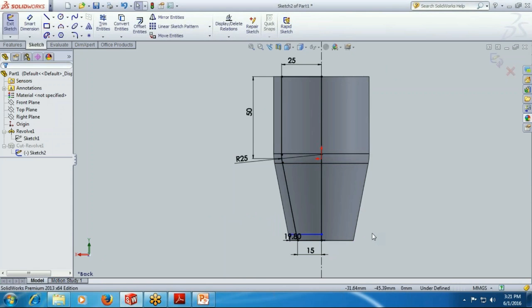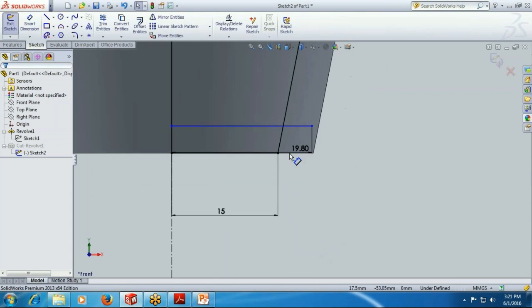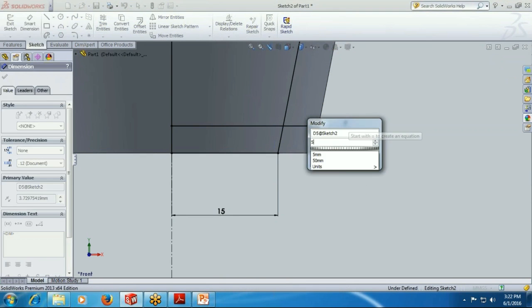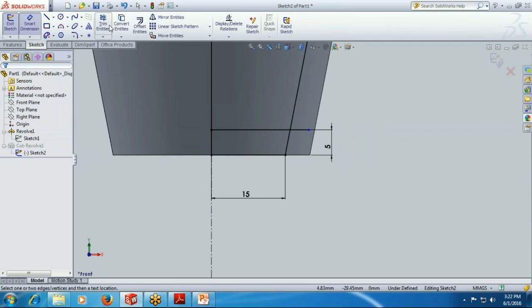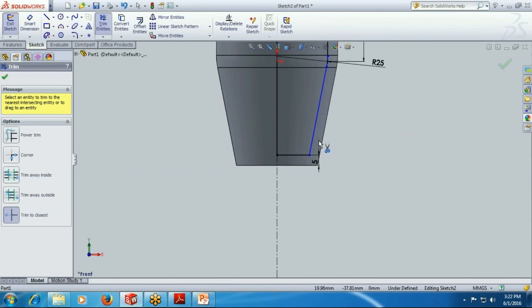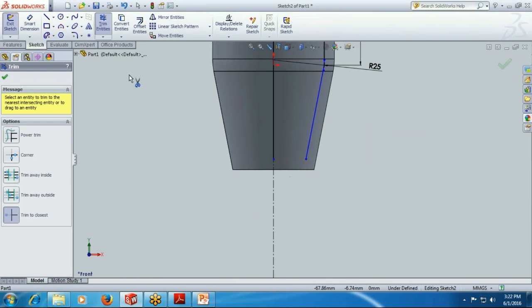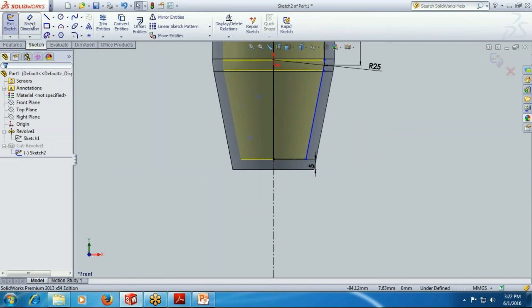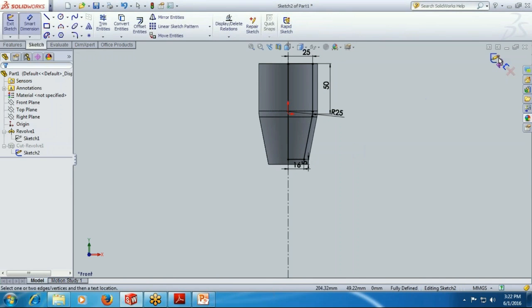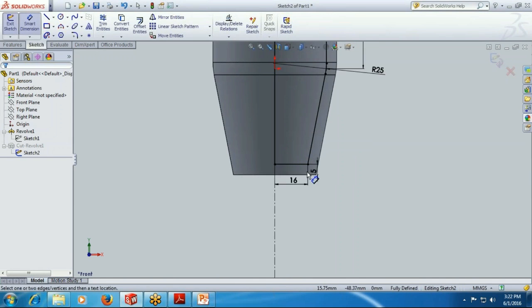Ctrl+Z, and after that the length I need to have now, so just give the overall length should be 5, and now make it trim. And this size should be given also 16 automatically.